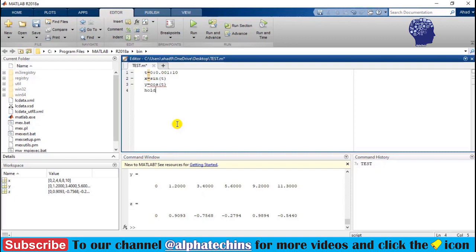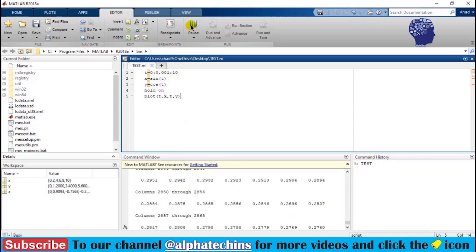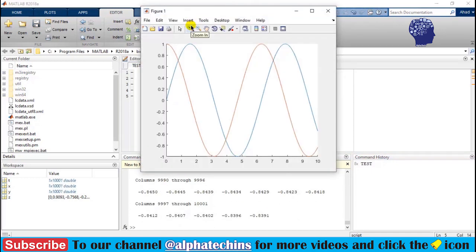Now I will use the hold function, hold on, and now I will use plot t, x, and you can also add two more variables in the same function like t comma y. Now I will run it. Here you can see we have added two functions on the same graph.